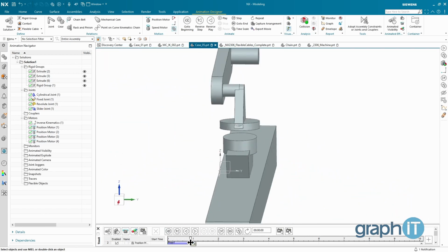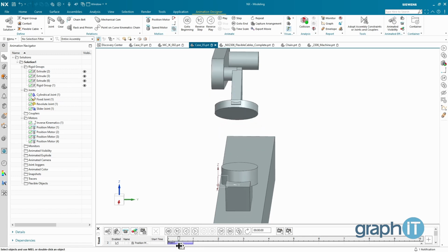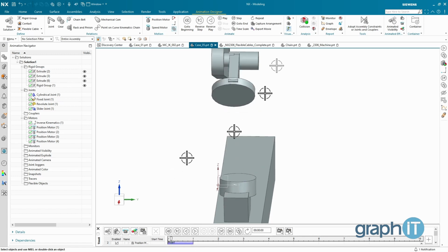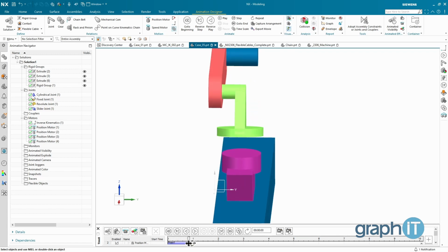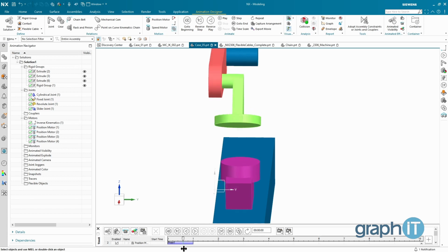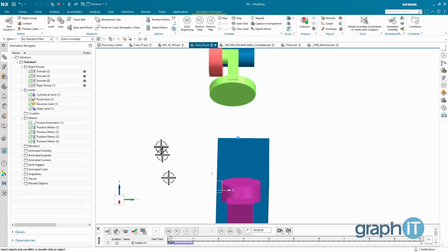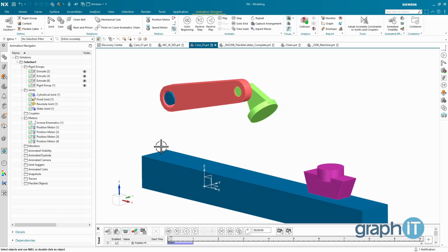Not only does the part rotate properly, but notice how it has to slide across to meet the conditions there. If you change my color on, you can see exactly what the green part is having to do, how it rotates and slides out. We did that with a cylindrical joint. Keep that in mind: you may have to use different joints than you're used to in the past to allow things to solve. Inverse kinematics, whether you're using one body or two body, doesn't work on every single joint.